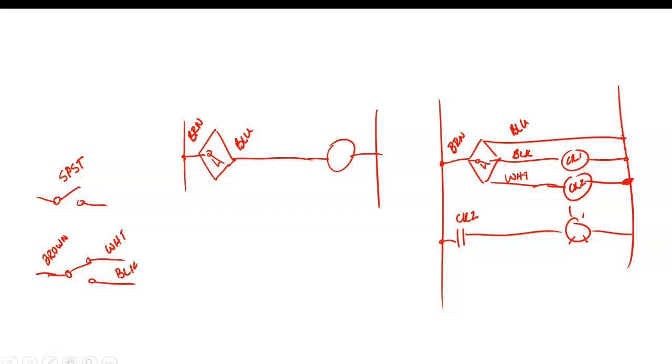And our temperature sensor is an RTD, which is a what? Yeah, and what does that mean? The sensor actually varies its resistance with temperature, but it's electronic, so we've got the threshold circuit inside there, and it's got a span we can set.